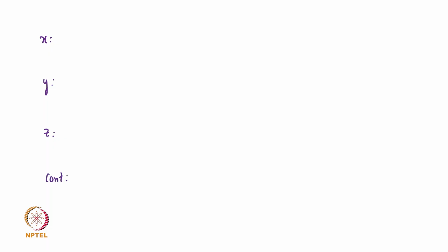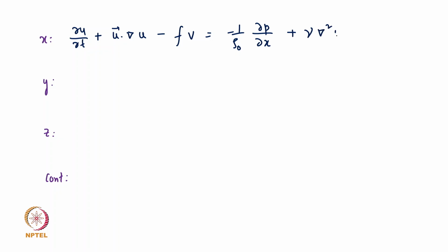The x momentum equation has the form del u del t plus u dot del u minus f v equal to minus 1 by rho naught del p del x plus nu del square u.